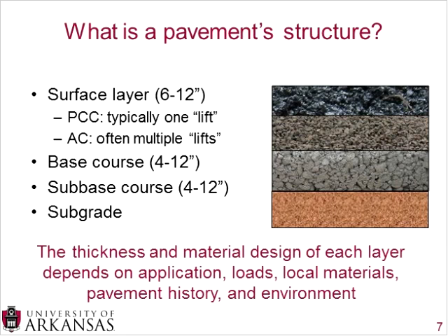The application that you're putting in, again, is this a highway? Is it a county road? Is it a surface street? Or is it an airport? Something that sees very different loads. And that goes into, you need to account for the loads that are applied on there. A residential street usually sees cars, maybe one truck or two every once in a while, versus an interstate sees a lot of heavily loaded 18-wheelers. And then of course airports see planes, anywhere from small turboprops to jumbo jets.